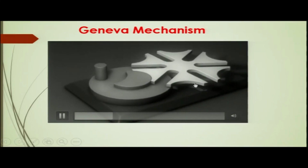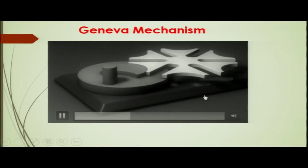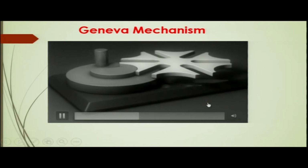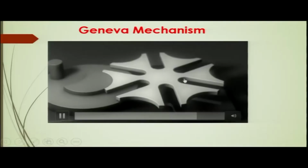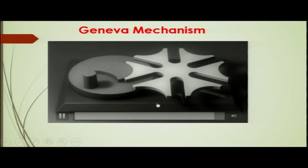Okay. So, let us assume that each of these positions is a position where the sub assembly is to be indexed, and it has to stay for some time for the assembly operation to be performed. That time is called the dwell time in technical terms. So, this can be done effectively by the Geneva mechanism. The only thing here, as you can see, the negative point is that the pin is taking the entire load, all right.